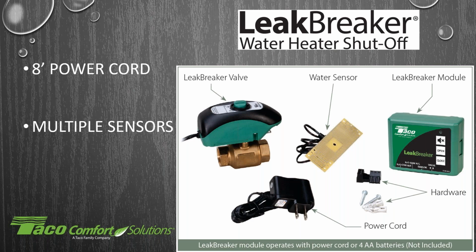We can put one sensor at the water heater, one sensor next to the laundry room, next to the washing machine, and another one by the dishwasher in the house, and you run those wires in series. So you can now have up to 10 sensors on one system. This kit is how you see it now, and you can add the sensors as you go along. You can use regular 18-2 thermostat wire up to 200 feet away from the controller. You connect your sensors in series on the terminal block that we have on there, and I'll show you the next slide in regard to that.